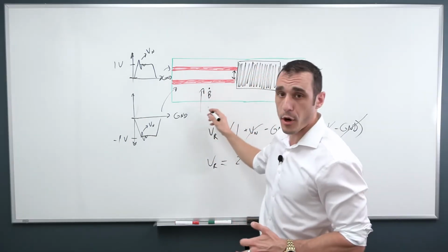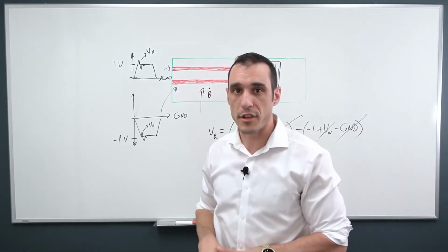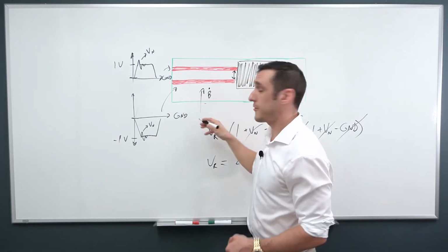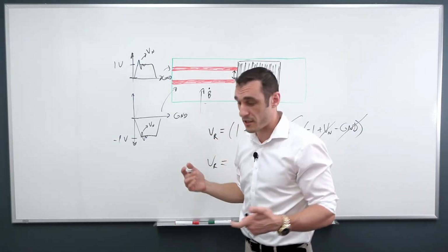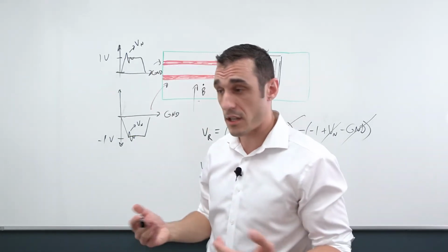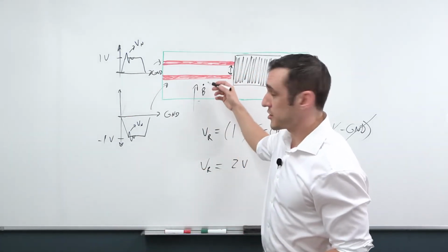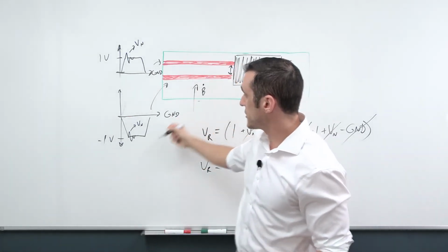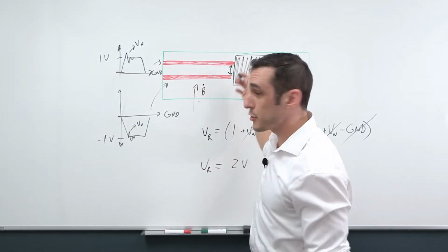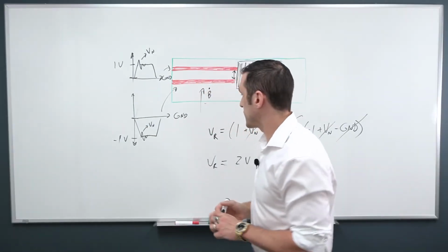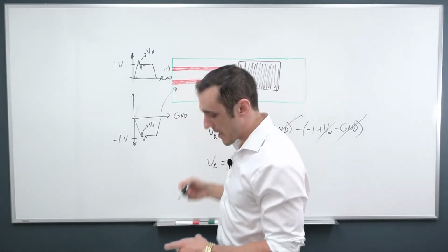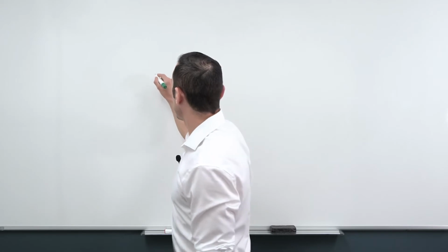So when I say some other part of the system, that could be some other digital protocol that's running with a single-ended trace, which would then produce this type of changing magnetic field if it switches very quickly, so if it's running at high speeds. Another great example would be a power converter. If you have a switching converter, those can emit a lot of radiation. If that radiation couples magnetically into these components, it would then also induce common mode noise, something like this that you would expect to see here. And so that can then also be canceled by the receiver. And so that's the main advantage of differential pairs, is noise elimination, and being able to overcome any changes in that ground potential.